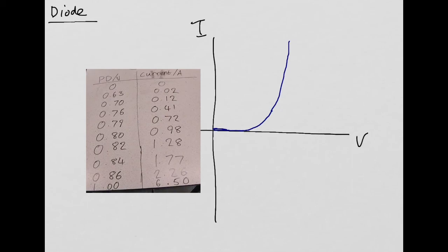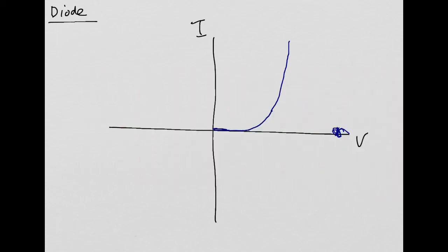We weren't able to go to these higher ends of voltages. If we managed to put 10 volts across the diode, then something's going to break, really. The current will get too high, the power supply will cut out, or the diode will break, or something else will break. So you see it goes up like this.